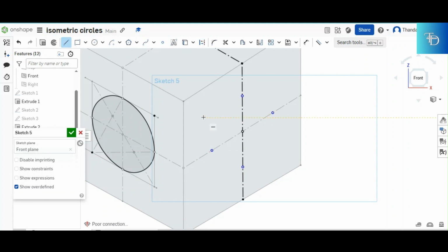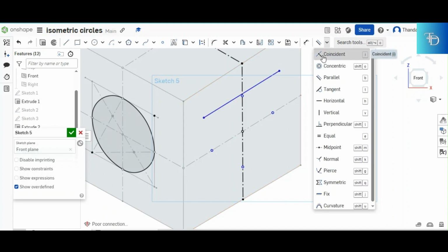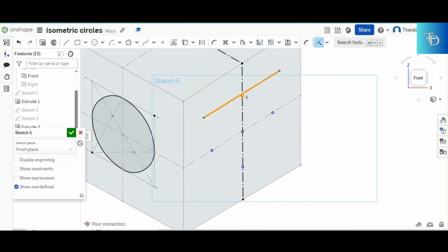And then the next thing you do, you take your 30-degree angled ruler, you create a parallel line right there that's going to pass exactly at that point. And then you do the same thing for the bottom point. And then your last step to complete the square, you close the remaining sides right there. You close it there, and then you close the other side as well.